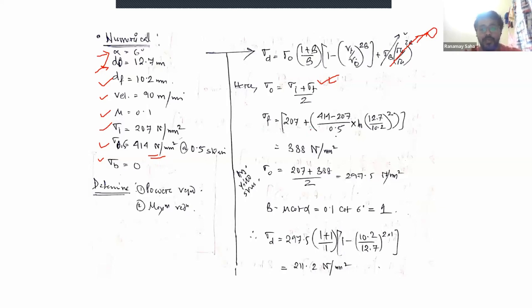So you plug these values into this formula, where sigma equals sigma initial plus the natural log of A1 by A2, initial by final area, which is the strain, times the modulus. When you plug in all these values, you find that sigma F becomes 388 megapascals.